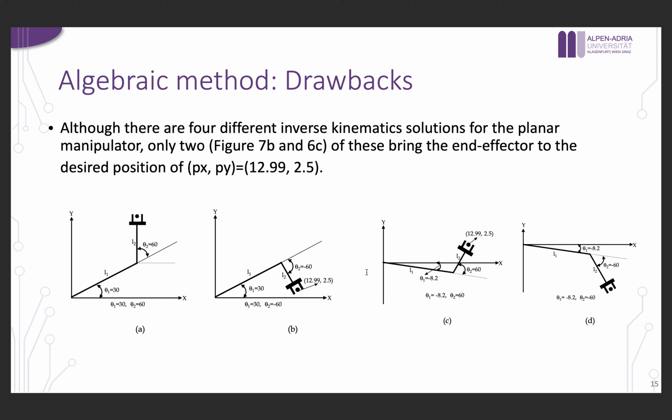of the solutions is to look at the robot arm itself and see the limits of the degrees of freedom. For example, like your shoulder as a human, the rotation is not 360 degrees, because there is a limit to rotation for each joint. Mainly the joints have 90 degrees actual working space. Some would have 180, and some, sometimes for the shoulder part, do have 360 degrees, but it's also not that common.